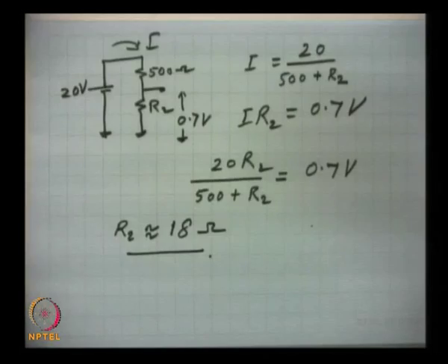I wanted to illustrate two points. One is that the half circuit is sufficient for the analysis of push-pull amplifiers. No matter how complicated the analysis is, it is always done with the half circuit. And the second point was that simple methods are there to calculate these parameters.